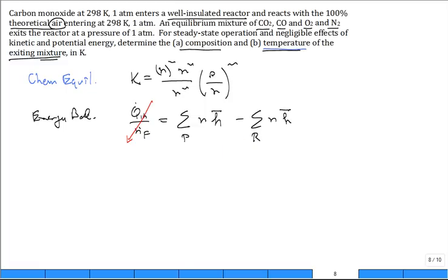Now you bring both of those to bear to calculate the equilibrium composition, which is going to be temperature dependent. Why is it going to be temperature dependent? This K is a function of temperature. So the higher the temperature, typically the way they write the equations, the more forward the reaction is, the more things that are on the right-hand side of that chemical equation are in the equilibrium mixture. There's more dissociation at higher temperatures. And that temperature is solved for with the energy equation.